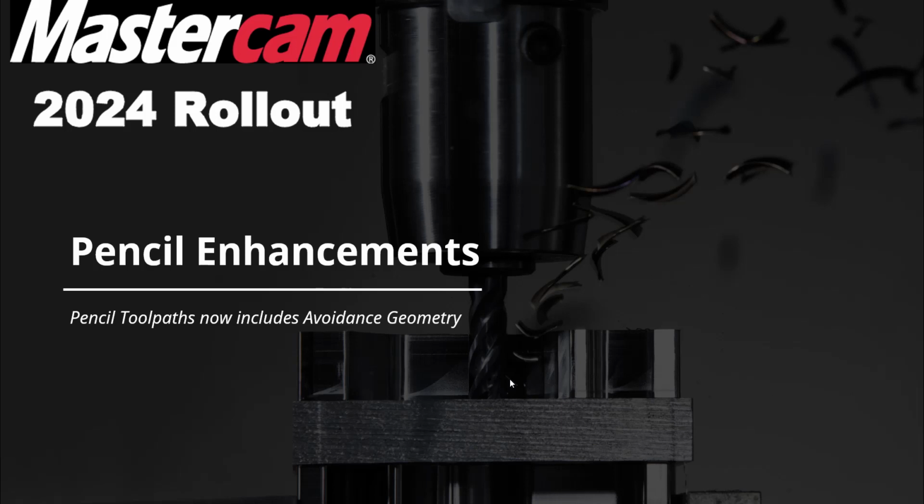And if you had any cusping in the corners, that was the worst stuff to polish out. So it made polishing so much easier. If you're not polishing, you can get a single pass down through the corners. It makes just a much crisper, nicer looking part. Doesn't add a whole lot of cycle time. It's got some options in it to make it a viable alternative to finish remachining.